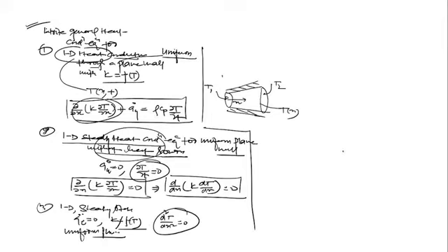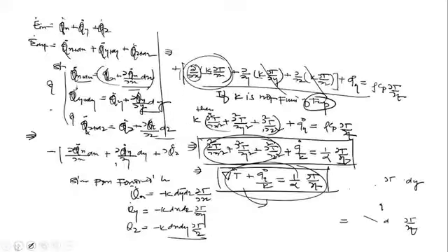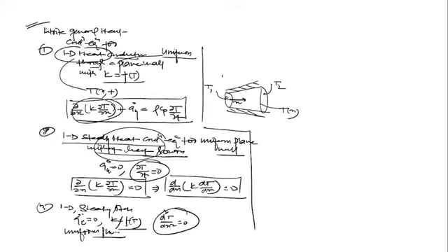So how will you write the equation? Since we have to write the temperature variation in x direction only, we should not write y. So I can go through this here, but here I should know area is not dx dy, area is only pi r square, normal direction of heat transfer, है कि नहीं?